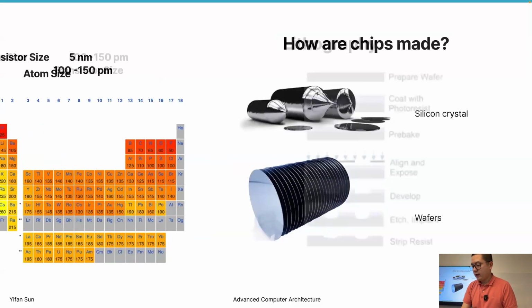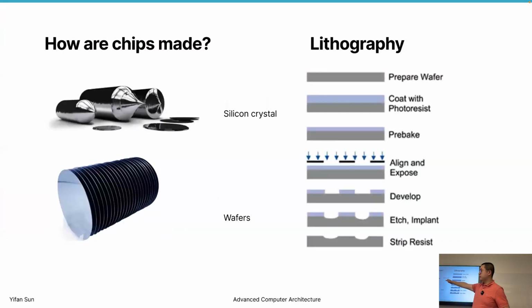So how it works is we first produce the chips on there, then we slice them. Okay, make them smaller ones. And how these chips are manufactured is a process called lithography. If you have heard of this company called ASML, then those are the masters of lithography. They produce these tools that are so precise that they control atoms. So how is it done? Now we prepare a wafer, right? We slice it. It's super clean, using a lot of pure water to clean it.